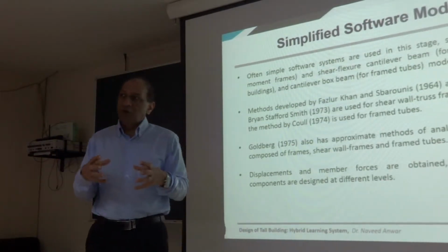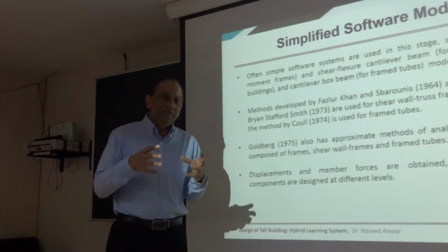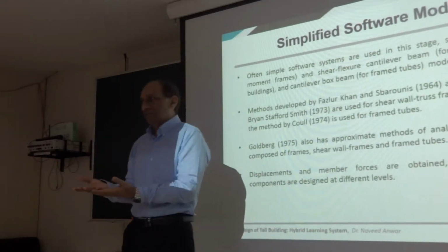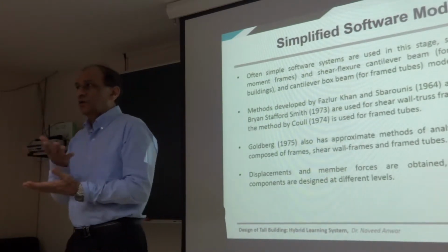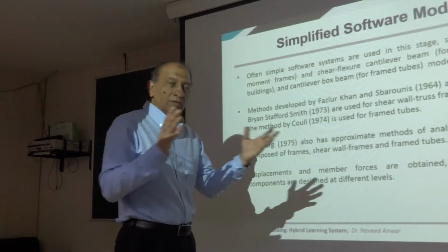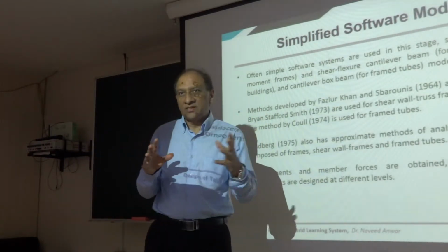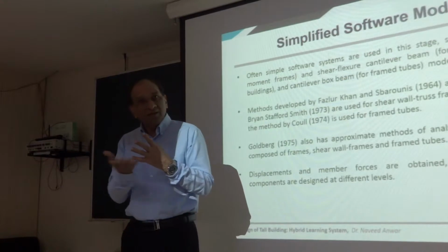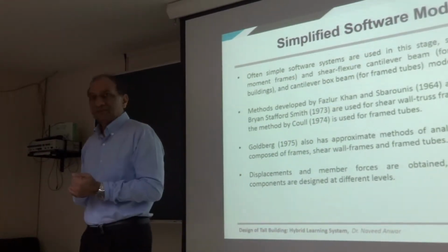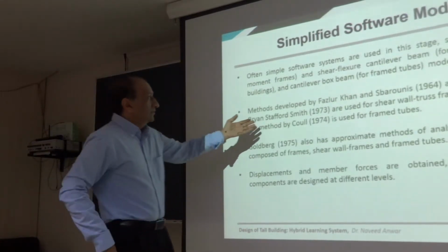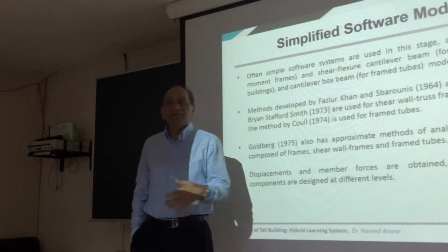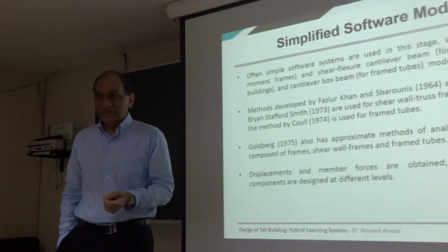So normally we do not want to involve the gravity load system to be part of the horizontal force system. We want to find a system for the horizontal loads which is independent, does not depend or rely on the floor system. And that is where these gentlemen, Fazlur Rahman Khan and others, developed some nice techniques. We will talk about that.